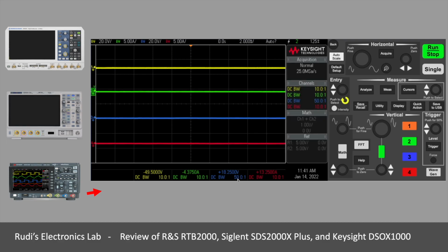We get to see the 50 to 1 probe. We have to do that via presets on this device, but the 50 to 1 preset fortunately is there, even though we cannot do custom. And the other current probe here. We get to see the same information for the channels here, and again we see all of them are bandwidth limited to 20 megahertz right now.